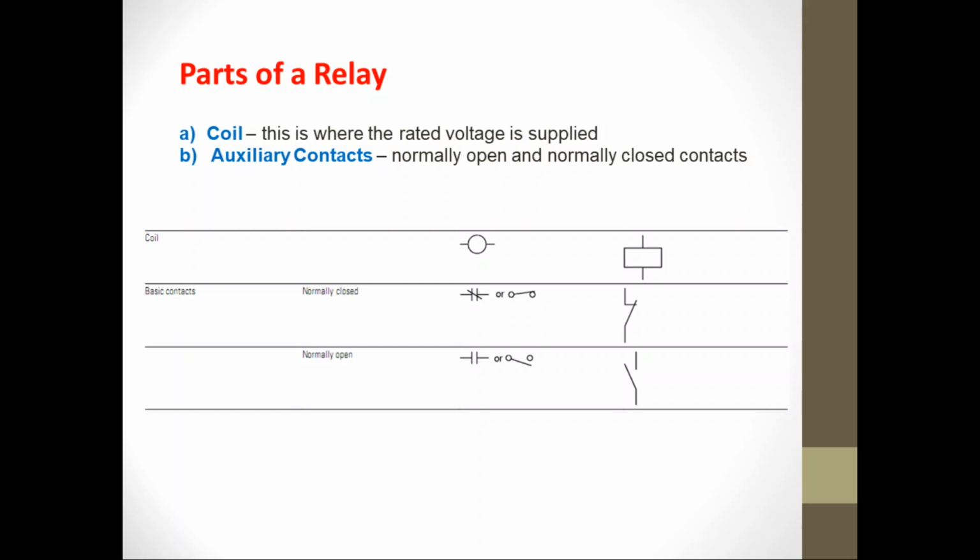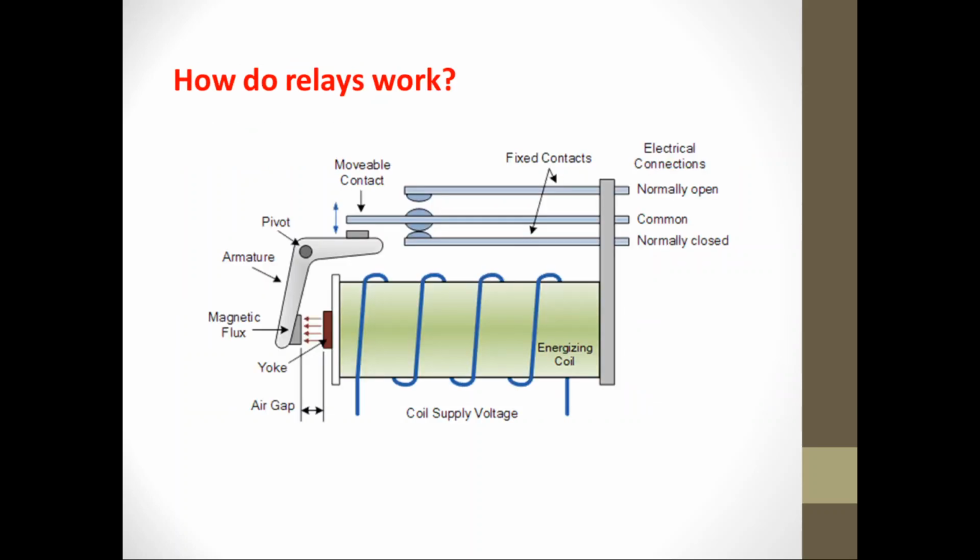So let's take a look at how a relay works. Focus your attention on this side. Initially, you select the common point and this other point. Looking from this point going to this point, it is actually normally open.